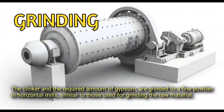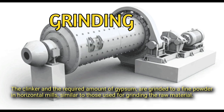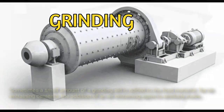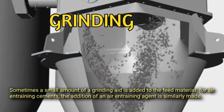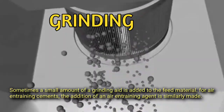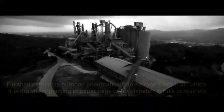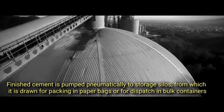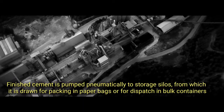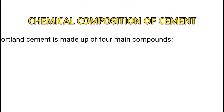Grinding. The clinker and the required amount of gypsum are ground to a fine powder in horizontal mills, similar to those used for grinding the raw material. Sometimes a small amount of a grinding aid is added to the feed material. For air-entraining cements, the addition of an air-entraining agent is similarly made. Finished cement is pumped pneumatically to storage silos, from which it is drawn for packing in paper bags or for dispatch in bulk containers.